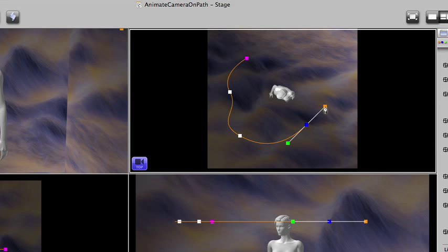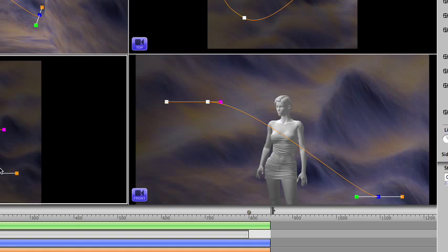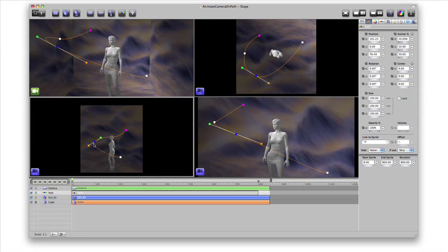In this view, we're looking down in space on top of the object, so we've created a camera that will go around the object in an arc. After the path is drawn, we can adjust the points. When I adjust points in the front and right panes, you'll see the changes in the other panes. I'm moving the path of the camera in 3 dimensions.